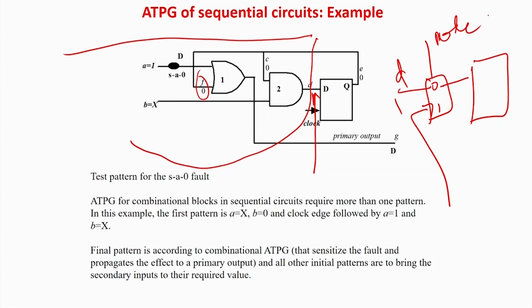So if you make the mode of test as 0, the D will go as the input to the flop, and if you make mode of test equal to 1, the output value you can put in and directly control the flip flop. So anyway, this is fine. You will require a lot of pinouts. This story will remain the same as the set reset problem, but that is what is required.